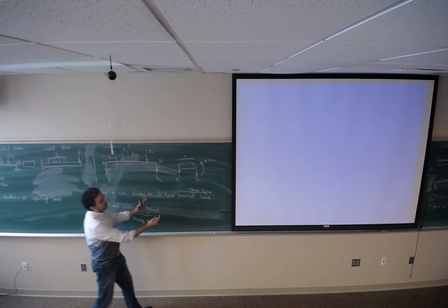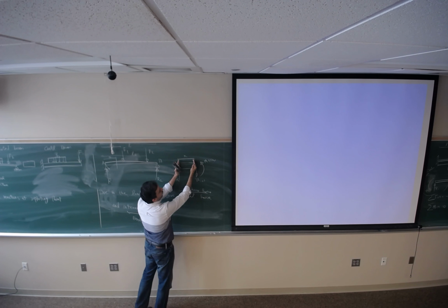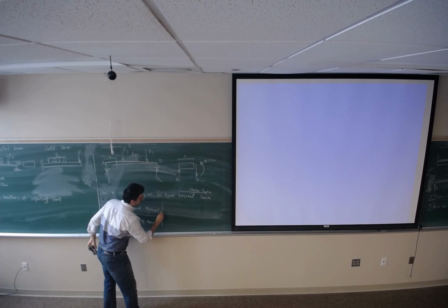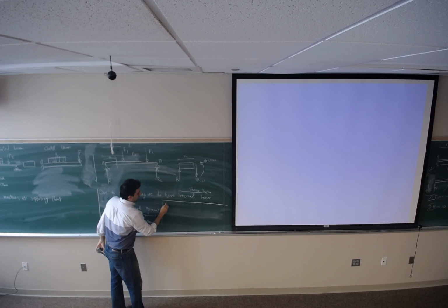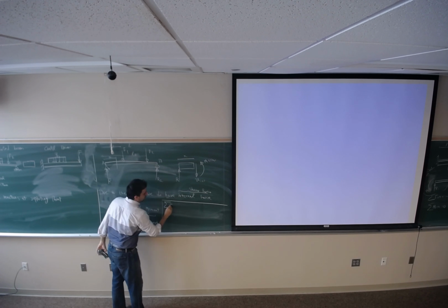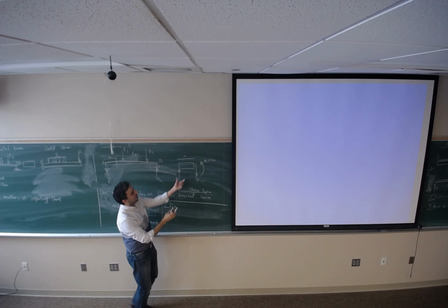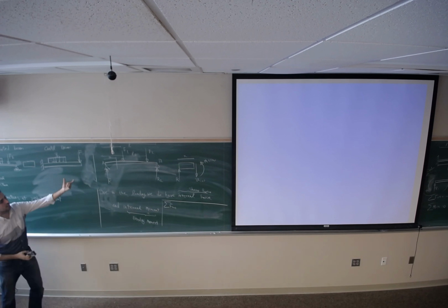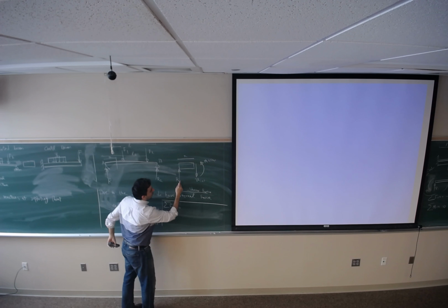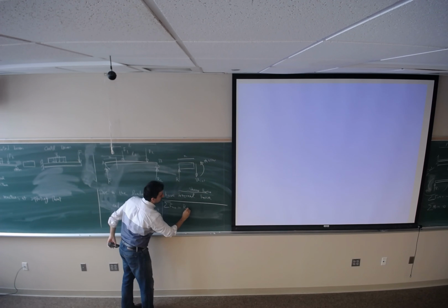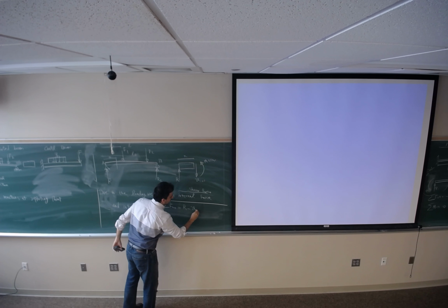Then, for this section that I cut, I'm writing the same equations. Summation of the force should be equal to 0. Why? Because this section that I cut doesn't move. So it's going to be R1, which goes up, minus V equals 0.